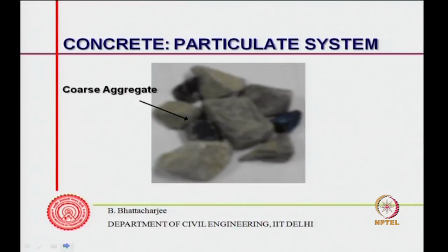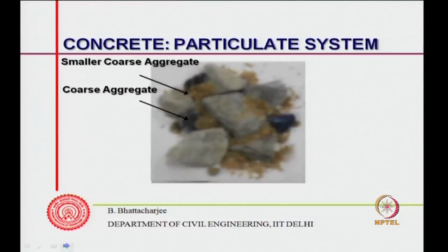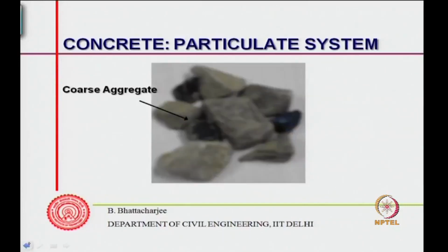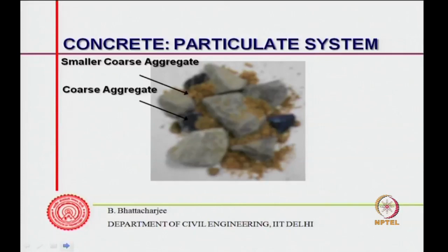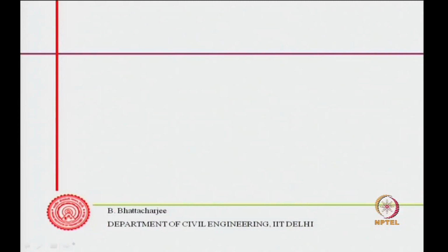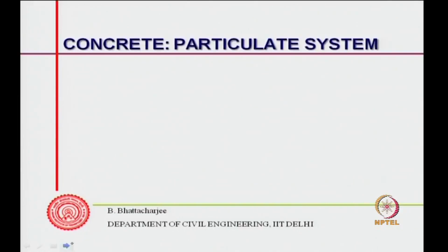Then the black ones, as you can see, are the finer aggregate, right. And now the interstitial voids are filled with the finer of the aggregate system, black ones, and now still the gap within will be filled in with some sort of fine aggregate, which in this particular case is sand. And all this put together makes the concrete at the hardened state, which will look like this.